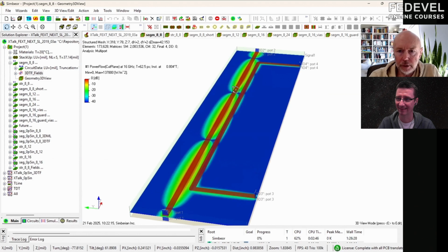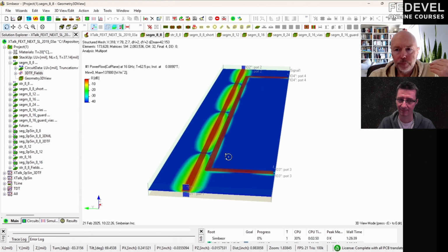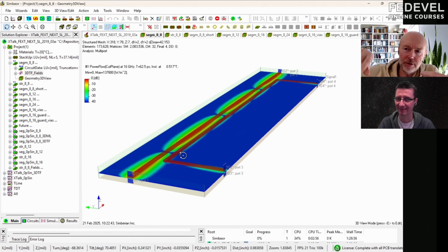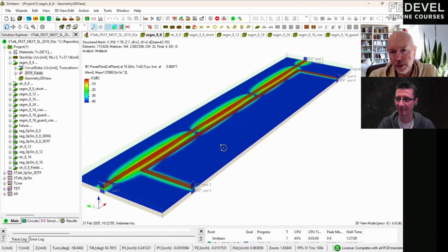In theory, the signal along those two coupled traces propagates not as a signal just along one trace, but as a superposition of four dominant waves. In this case, even and odd mode, traveling in this direction and traveling in this direction. And this superposition gives us near and far crosstalk. That's why you see in the frequency domain this behavior where you have maximum, minimum, at half wavelengths, quarter wavelengths, and so on. That's the result of this superposition.